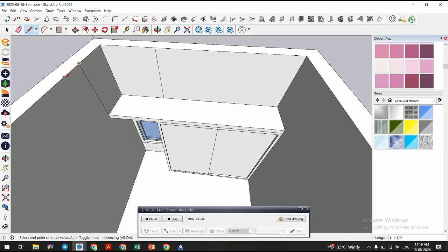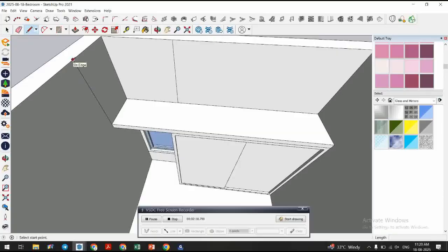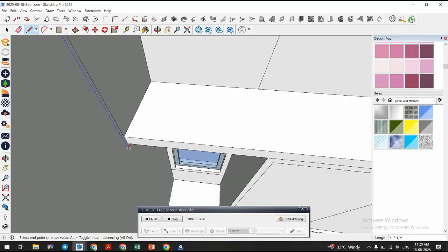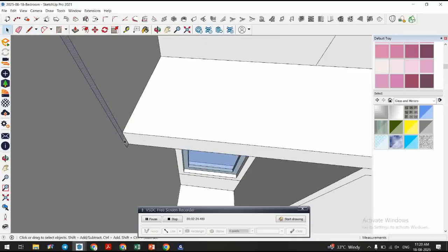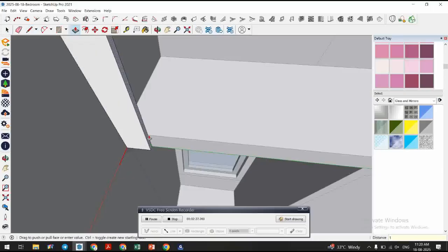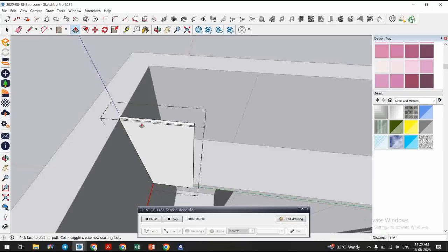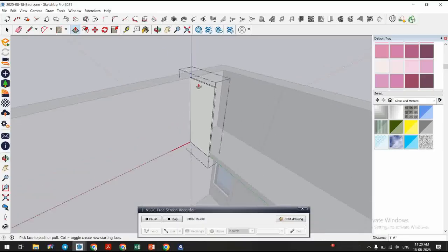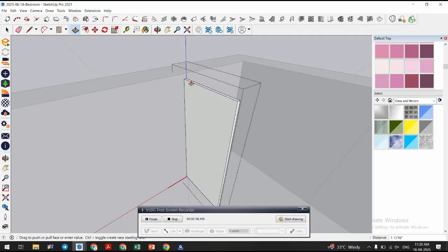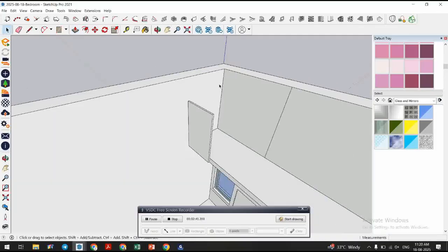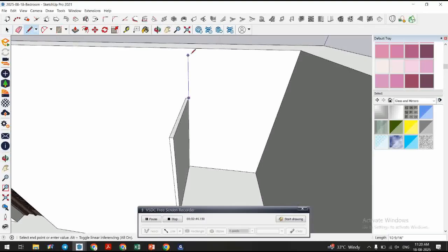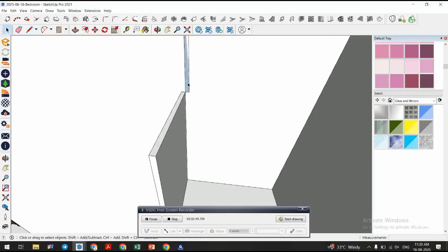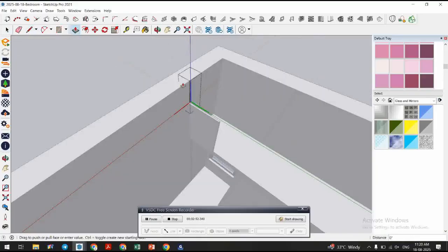So I'm just going to create a single door. Usually the minimum width of the loft door will be 1 feet 6 inches. And since, when it comes to the bedroom, we will be designing with the false ceiling, for which I am offsetting 1 feet of depth. Behind this you will be having another plywood which will be acting as a partition to hold these doors.